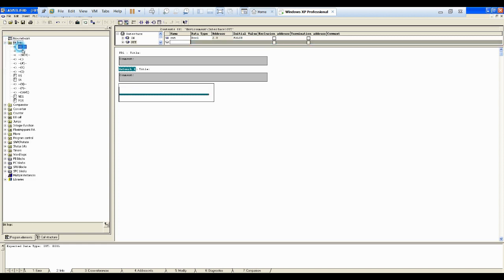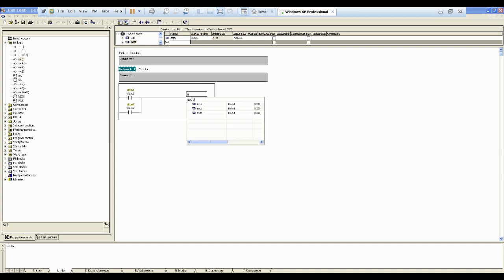Go ahead, bit logic, select it out. We want to have in parallel, so we have to select here, move this branch down, take another input and make it up from here. Now our architecture, our network is ready. Just put in1 and in2, and we have output. Okay, now that's not Q0.0, sorry for that, it's output here.